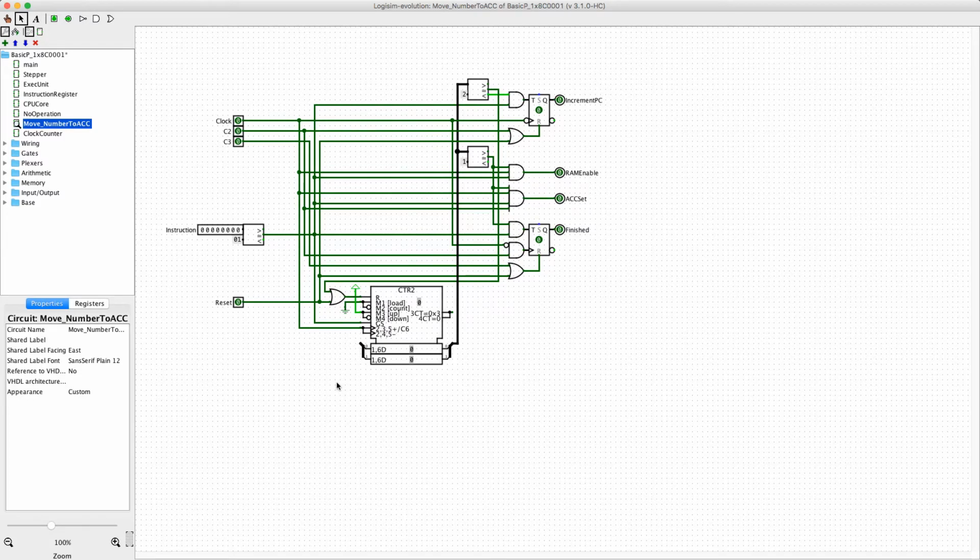There. This is what the component originally looked like when I was still using the clock to control the set wires. So instead of using the enable and then writing the data on the next clock cycle, I would use the clock wire directly as the set wire, and that's what all these flip-flops are for.